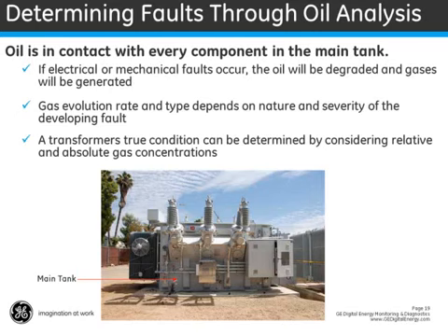One example is Perception, a platform from GE. Designed as a fleet management tool, Perception is capable of performing transformer risk analysis. It can be used together with a DGA monitor, collecting data to evaluate the condition of a transformer and rank that transformer within a fleet based on its risk of failure.